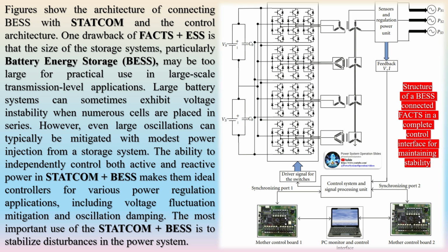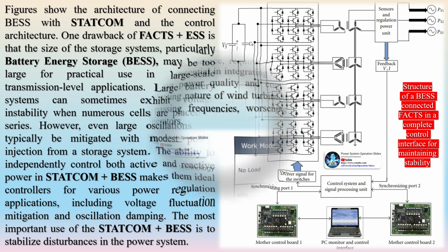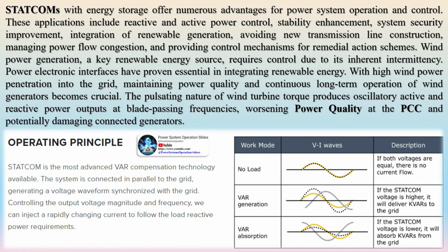DG systems. The generator can be sized to produce more power than the maximum capacity, with the excess absorbed by the battery. In cases where this situation is possible but not probable, the BESS can act as a dump load to absorb the excess power. STATCOMs can enhance stability even in offshore wind farms, which are often weakly connected.